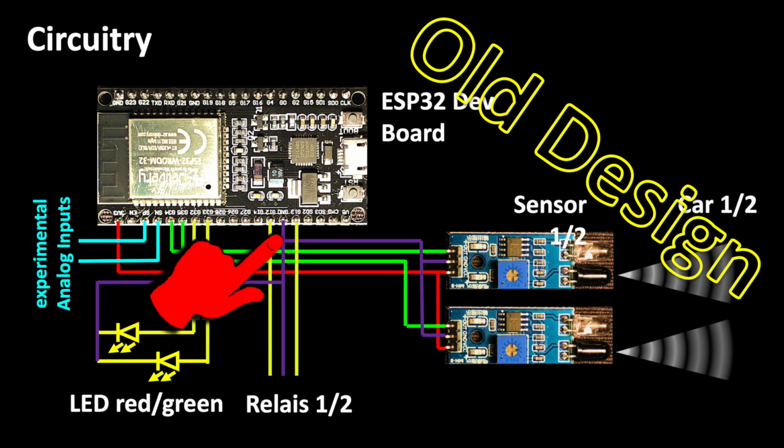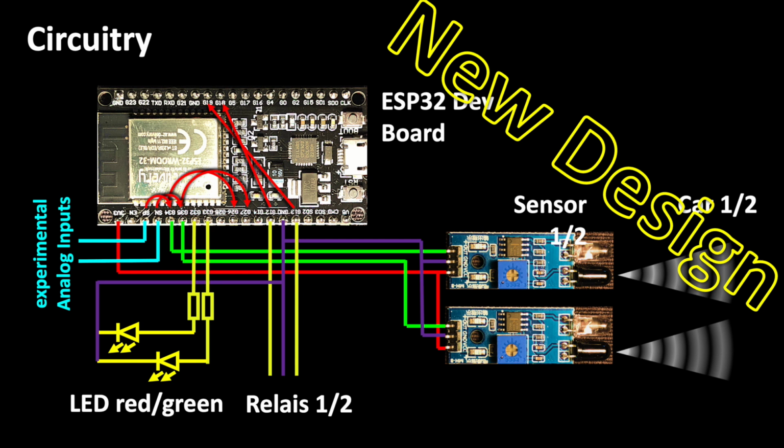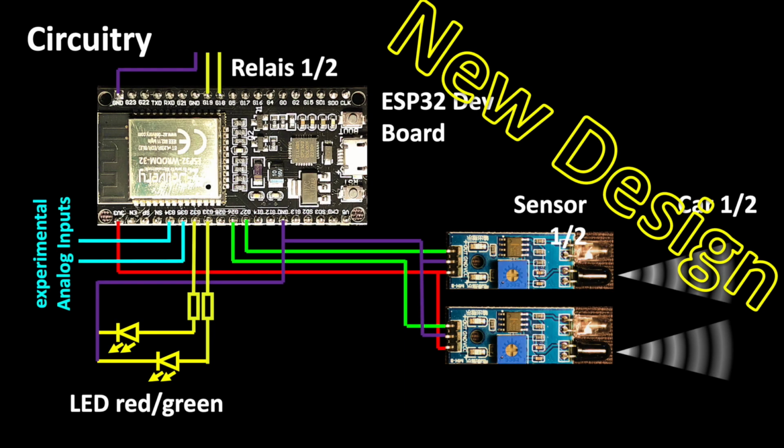The ESP32 board is a pretty complicated beast, and you know, something unexpected may happen sometimes because you cannot oversee everything at the very beginning. That's why I tested various pin assignments, and I will now show you the one that really worked without errors under all circumstances. Of course, the changes are also included in the new code that I offer for download.